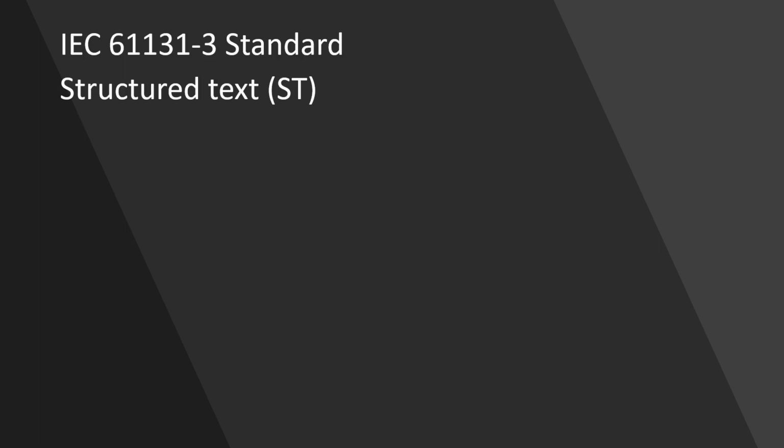In my opinion, structured text, ST, is best. The reason behind it is that it kind of feels limitless to me compared to other languages like FBD or something. It might be worse in some specific occasions, but if you need to do some complicated things, then ST would be your choice. And in my opinion, it's very good for general use as well. I mainly code with ST on a daily basis.